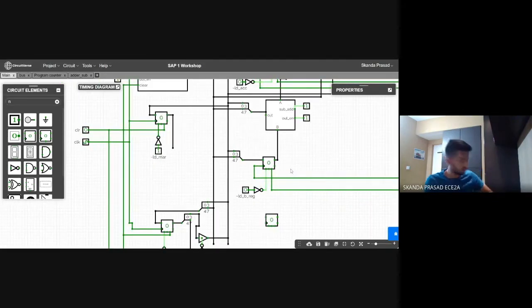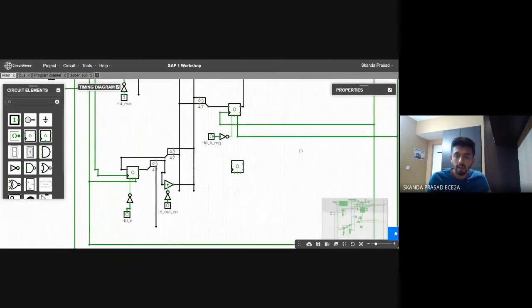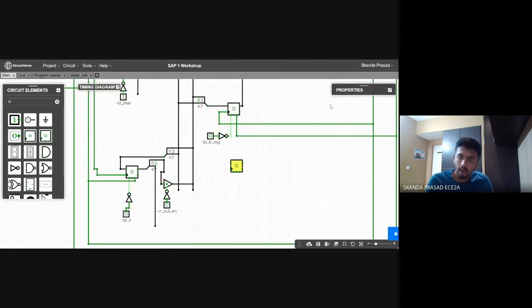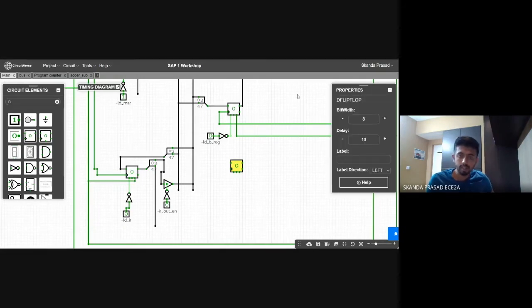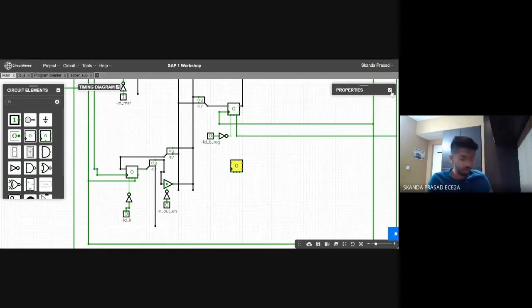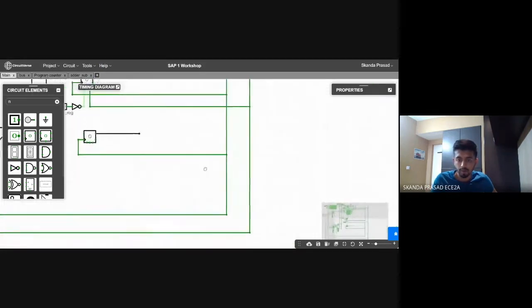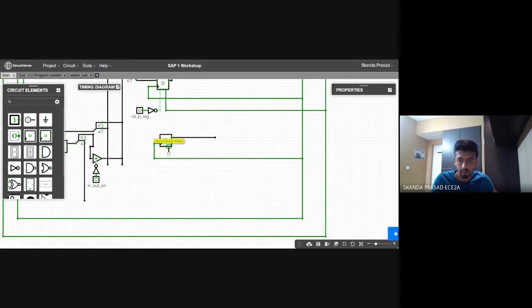So that is done, and all we need to do is the output of the B register, which is done, and yeah, so that's finally done. Now finally we come to the output register. So we are almost at the last stage, barring the memory. So that's 8-bit. We've already selected it. Now let's check what happened to the output. So I'll take the output, just keep it there for some time. Clock goes to the clock. Okay, that's clock done, and asynchronous goes to the asynchronous feature. That is clear. Are you clear?